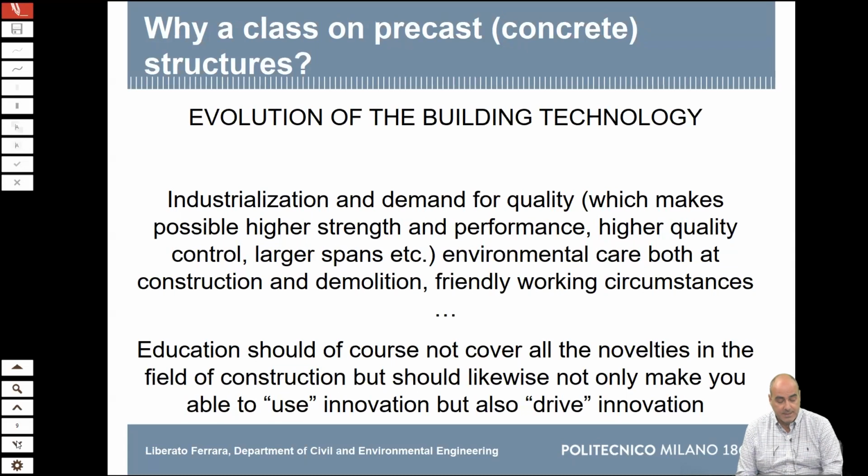And this also because there were other issues: how the construction industry could keep pace with the development in concrete technology. Self-compacting concrete was a great innovation in construction, and it's now regularly used in the precast concrete industry, because the precast concrete industry has the tools to implement the quality control in the mix proportioning, in the mixing and so on, that self-compacting concrete requires.